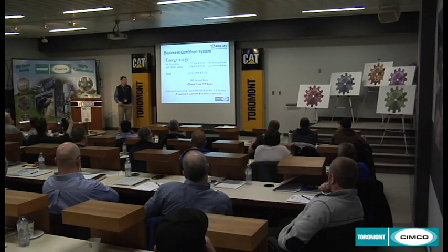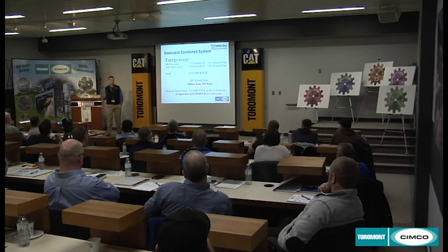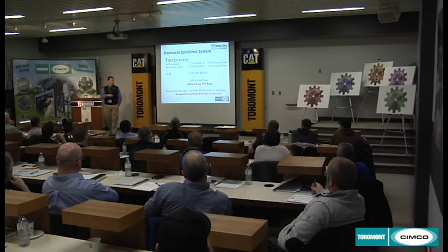Significant energy reduction. Now the desiccant does have to be reactivated, so we're adding energy that needs to be accounted for, but it was nearly a wash with what they were using for reheat energy. So those kind of counterbalanced out. They still needed to apply energy to reheat. We need energy for reactivation. So their actual savings was this number right here. Again, you can scale that down. For a 1,500 seat arena or something in that name, it'd probably be a 70-ton saving or something like that. But there's definitely savings to be had.